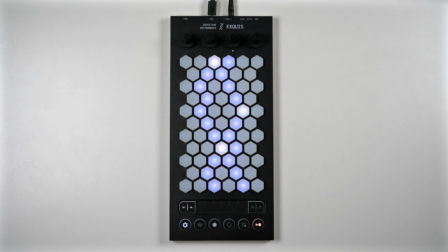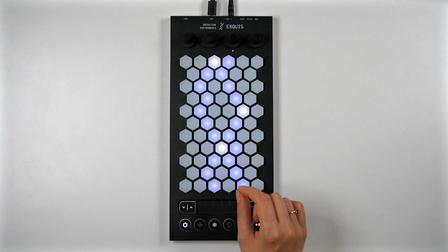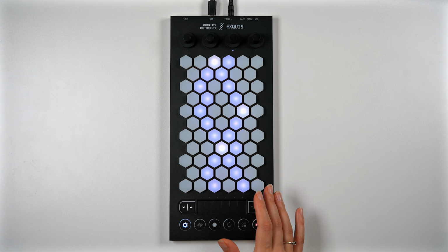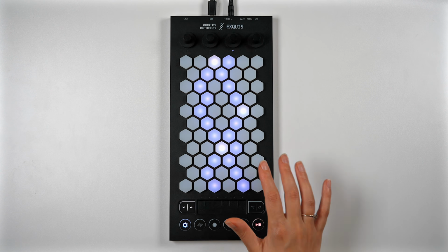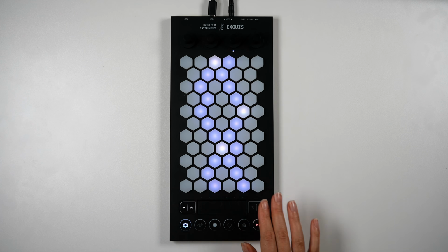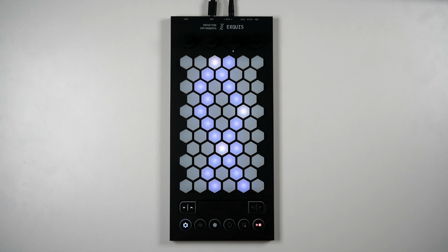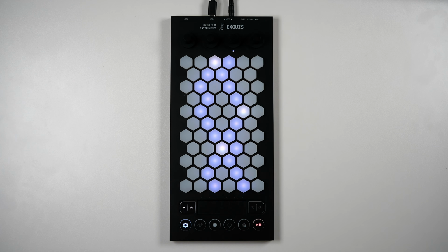As I mentioned earlier, the point of an MPE controller is that you have many different dimensions of control from each element that you make physical contact with. So instead of using knobs or sliders or pitch bend wheels to play expressively, you can instead use the way that you're touching the controller to alter many different parameters of sound. Each one of these hexagonal keys produces X, Y, and Z data. X is mapped to pitch bend, Y sends out CC74, and Z, or pressure, is aftertouch.